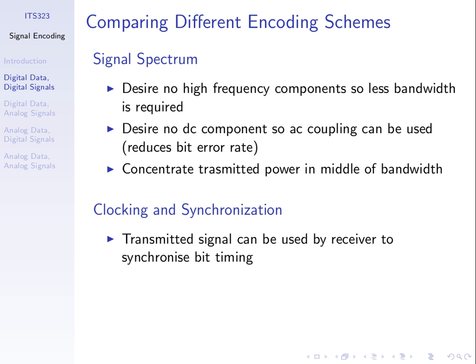The transmitter transmits for 1 millisecond each pulse, and the receiver thinks it's 1 millisecond, but in fact its clock is wrong and it's actually measuring every 0.8 milliseconds. As a result, it's possible that it will measure the wrong value for a particular bit.